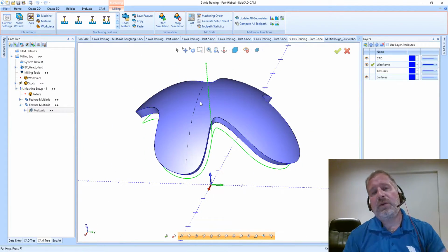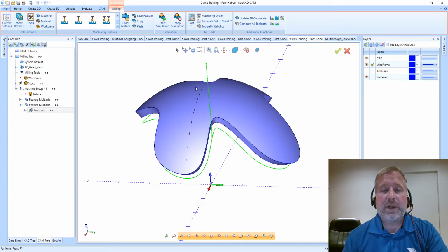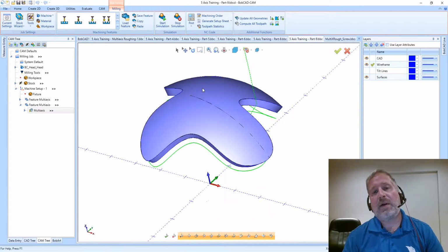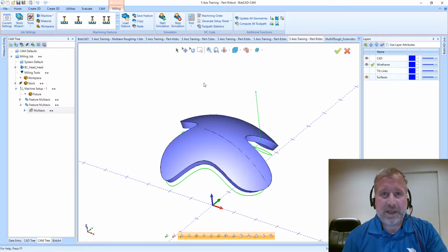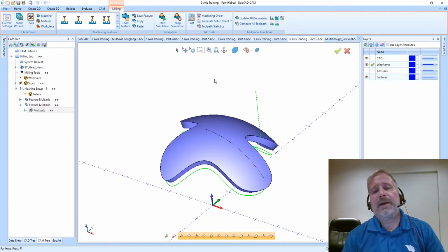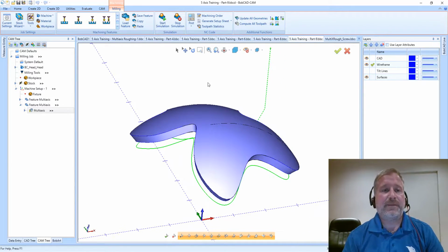And so if you need to cut through a piece of material and, using the side of the tool, go around and cut that part out. So think of a thermoformed part, a plastic part, a stamped metal part where you're trimming flashing off. It might be with an end mill, it might be with a laser, plasma, or water jet machine. Could be a router. This toolpath is designed for doing just that.